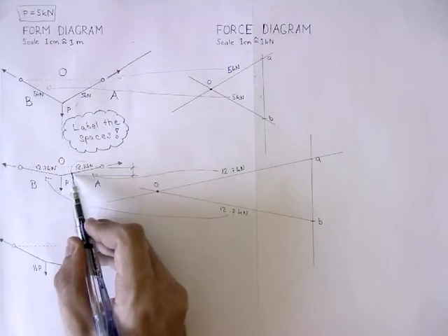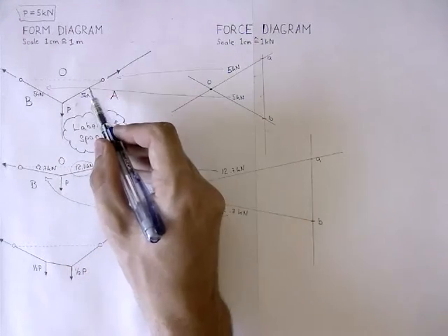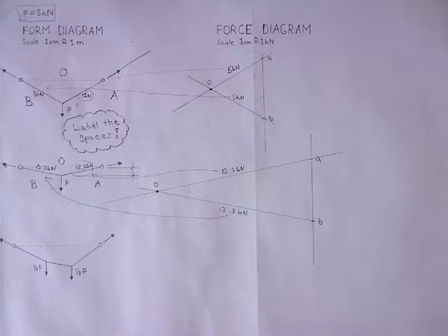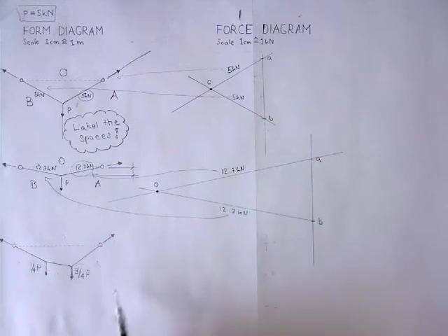Comparing the forces from this example with the forces from the previous example, we see that they have grown significantly. From that, we can conclude that the more structural depth you have, the smaller are the forces in your system. This is especially good to know if you have to design simple structures out of unreliable materials such as toothpicks, straws, or pasta. Now let's go to a slightly more complex example.